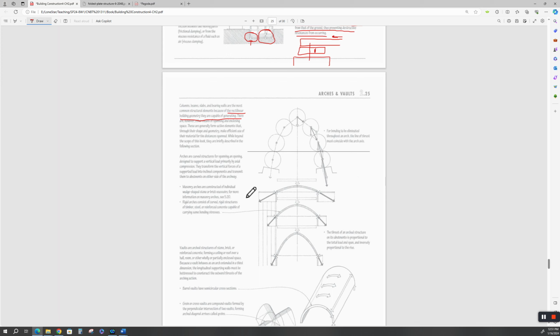And these arches can be made out of anything. They can be made out of steel, or out of masonry. The older ones, like the Roman arches, are masonry. They have a key block over here and a key block up here, and this is all masonry. If not, you'd have to have a lintel beam to carry the masonry horizontally, like a regular beam. But if you put an arch in, it'll spread the load out over a curved surface.